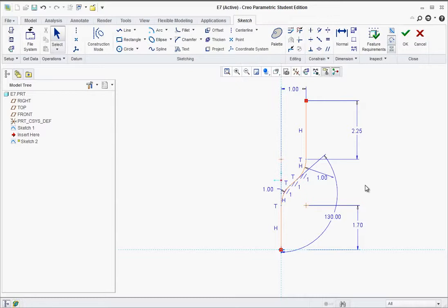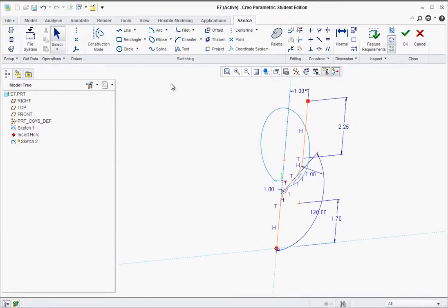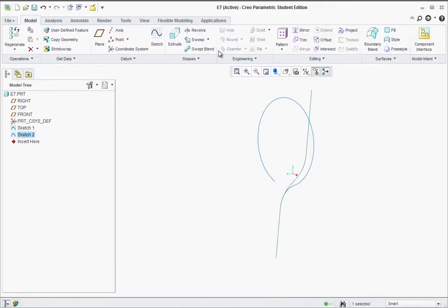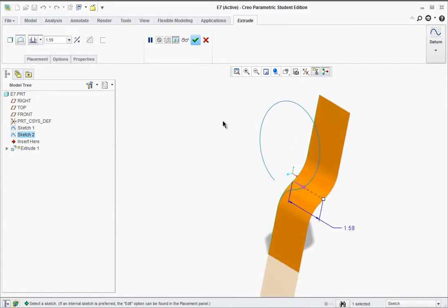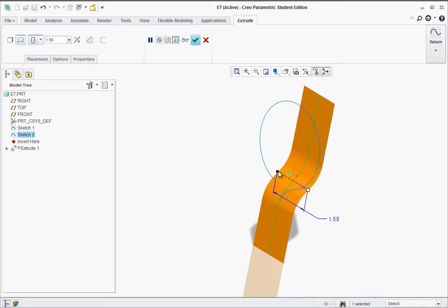At this point, I think we're ready to go ahead and we're going to extrude this. So go to the extrude tool, and we're going to make an extrusion, and you see it makes a surface. Now we need this surface to extend beyond the boundaries of that wire for this tool. So make sure extrude surface is on. It should be on by default. But then over here to the right of that, hit this little arrow and find the mid-plane option, which extrudes on both sides of the sketch plane.